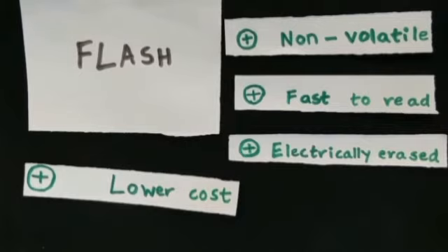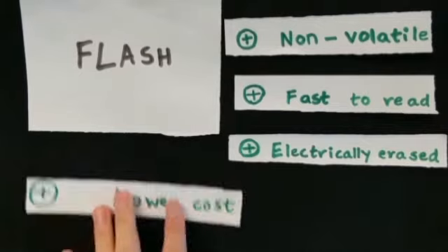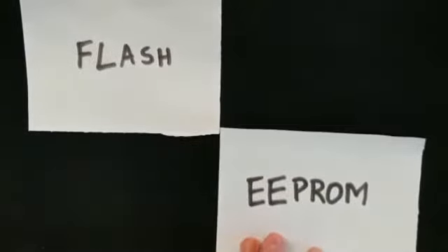How does flash memory erase one sector at a time, you may ask? Well, flash memory can only read or write an entire chunk or sector of memory at a time. This means that if the user wants to change only one byte, flash must also rewrite all the bytes in that sector. That means that flash memory can wear out faster than EEPROM.